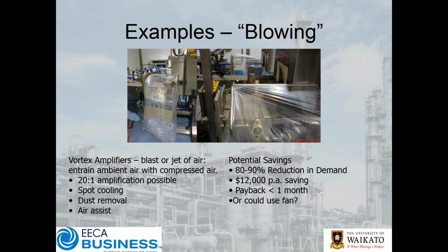For this one little application, it was a $12,000 per annum saving. The payback was under a month. It was such an easy gimme, but we had half a dozen quarter-inch compressed air lines. They were little push-fit fittings with no tube pushed in the end, just blowing air across the conveyor. It's just a horrendous waste of air.